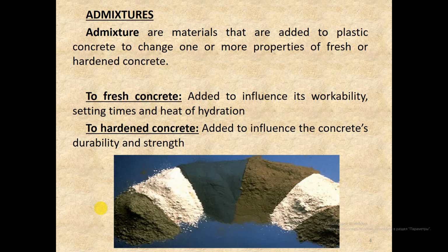An admixture is a material, usually a liquid, which is added to a batch of concrete during mixing in order to modify the properties of the fresh or hardened concrete. Nowadays, admixtures are added to most mixes, and in some cases they are essential.